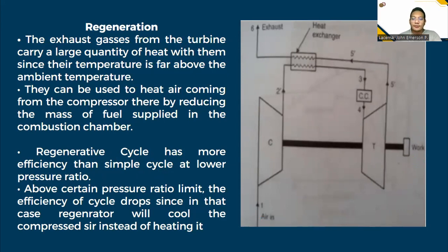Regeneration is a thermodynamic process that utilizes the remaining energy in the exhaust gases from the gas turbine to heat the air entering the gas turbine. Okay, so bakit nga ba nakataas ng thermal efficiency? Regeneration increases the thermal efficiency since more of the heat flow into the cycle occurs at higher temperature. Kasi i-regenerate, muli natin gagamitin yung remaining energy in the exhaust gases.